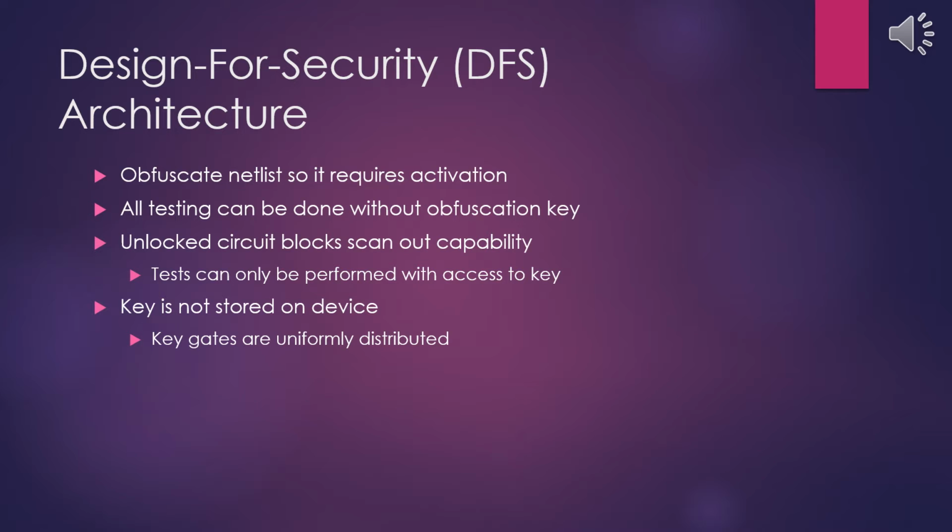The key is never stored on the device, which prevents it from being read from an unlocked chip. The key gates are evenly distributed across the design to better obscure the design and prevent logic-based attacks.